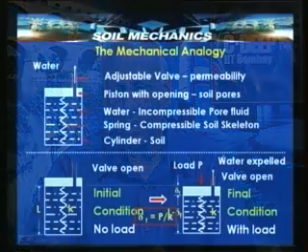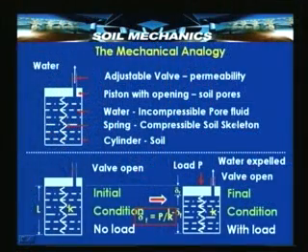So, here is a spring which is compressible and that represents the skeleton. So, this is the whole overall soil, this is the skeleton and this is the water, and these constitute the system as a whole, which is analogous to the system that undergoes consolidation and compression in nature.